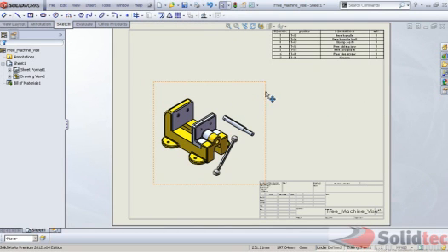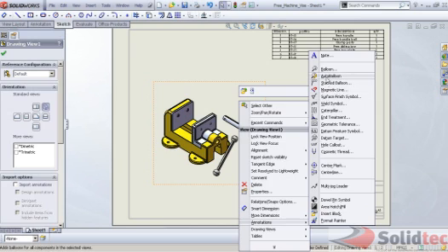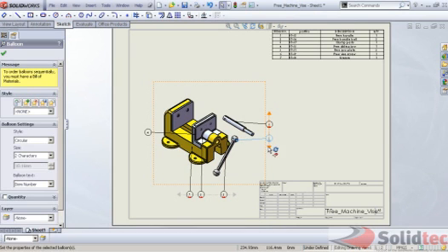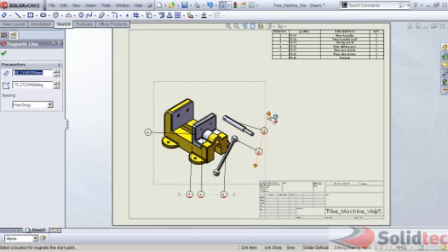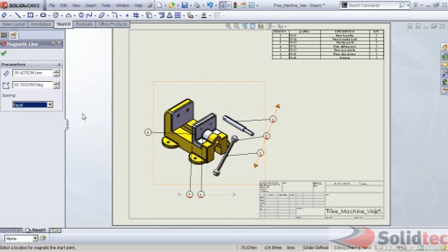No bill of materials information is complete without balloons showing where the parts reside in the model. So let's quickly add some balloon annotations. There we are. New for 2012, we have some magnetic lines that make orienting your balloons very easy. I can quickly change the direction and orientation of the balloons. I can quickly snap existing balloons onto this magnetic line, and I can also tell it to space the balloons equally on the line very easily and quickly.